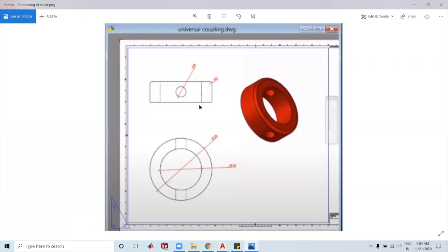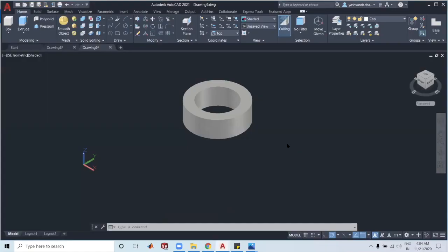And as you can see over here, there are these curved edges which have been added to the cap. So this is what we commonly call the fillet feature, and they are of radius 1 unit each, and they've been added to the top as well as the bottom. So I'll just add those fillet features.